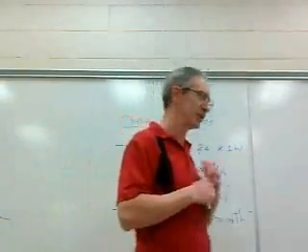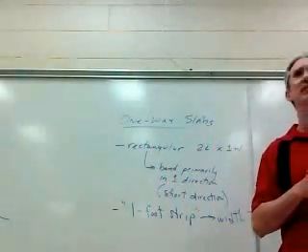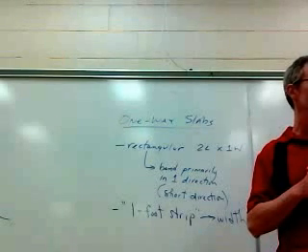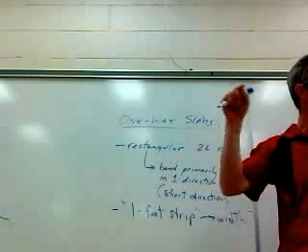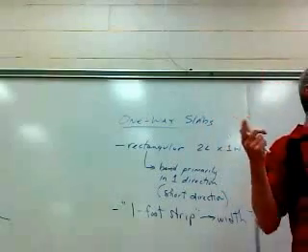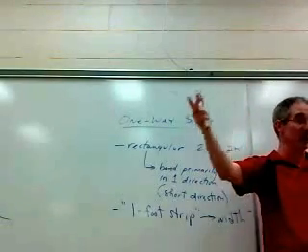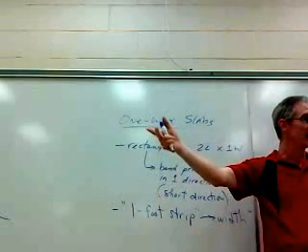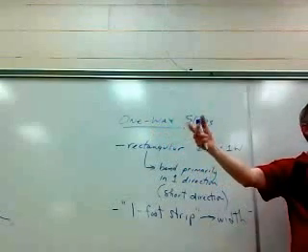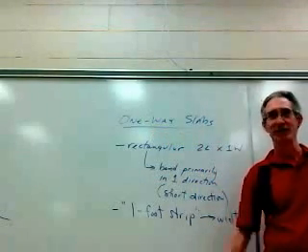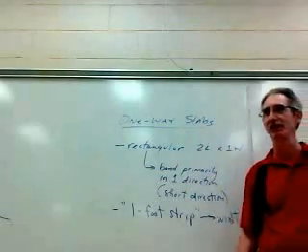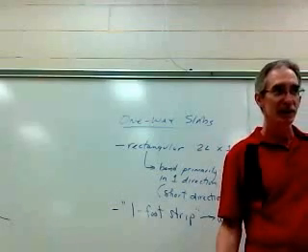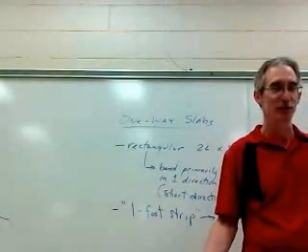Well, and it might use decking too, but again, we're just talking about the concrete. The steel's going to be given to you in a center-to-center spacing, right? Have you ever seen a plan that says, hey, we got 68 number 4 bars at 6 inches on center? But a lot of plans will just say you got number 4 bars at 6 inches on center. It's up to the rebar fabricator, the contractor, the estimator to figure out how many bars they actually need. Okay? So a lot of times you just have on-center spacings for rebar.